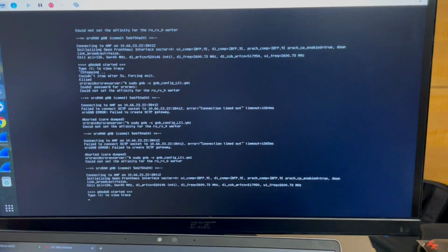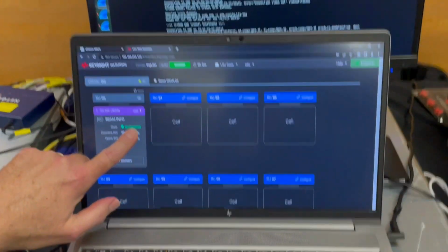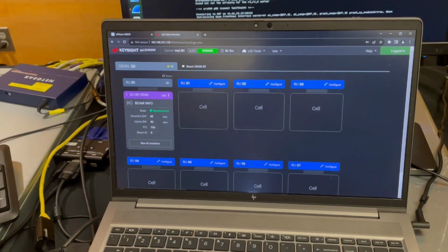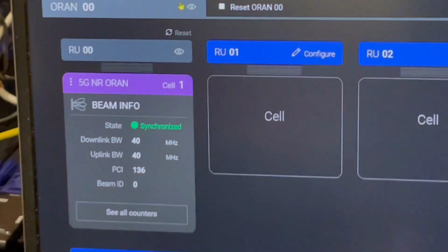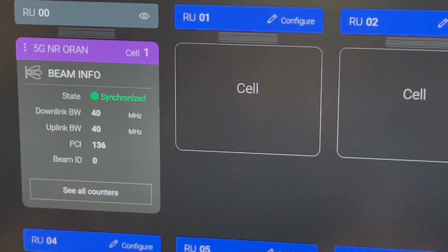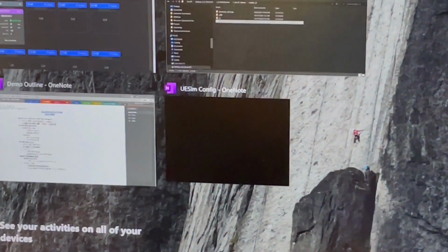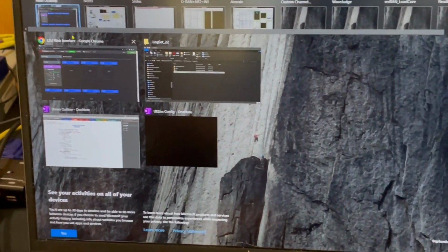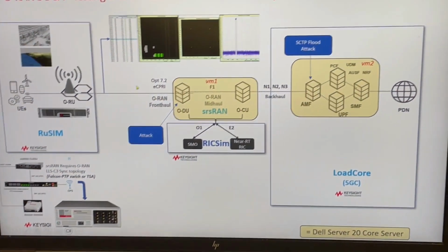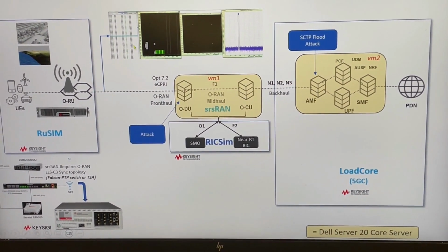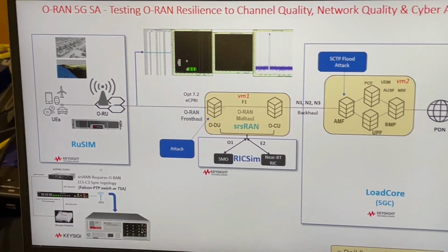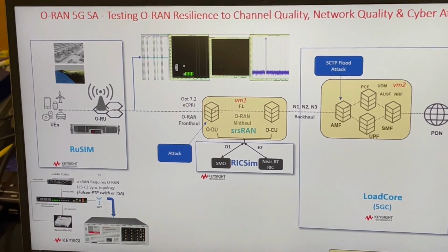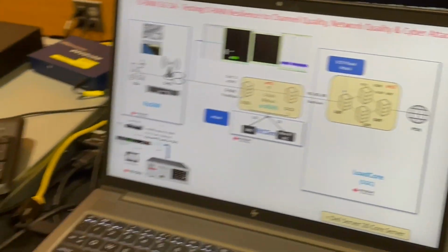It was happier. Okay. And now you can look over here and see that before we had no signal, but now this says synchronized. Yes, it does. So this means we're synchronized to the system, and synchronization blocks are being transmitted on the downlink. And in this environment we can tap off here and feed our WaveJudge software, which does protocol analytics from the IQ data, from complex numbers all the way up to layer 4.